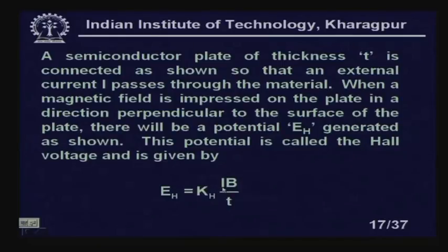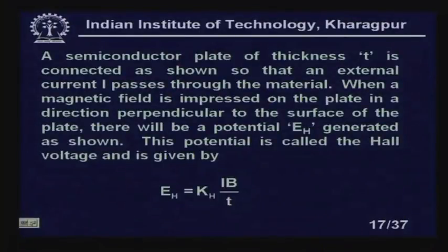That is the reason Hall effect sensors are extensively used for measurement of large current, very large current, around 500 amperes and all those things. Various types of Hall effect sensors are also used. And moreover, suppose this I is constant, if I can vary B, I can use this Hall effect voltage EH for a proximity sensor. Clear? How? Let us look at it.